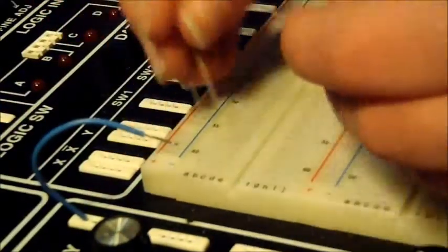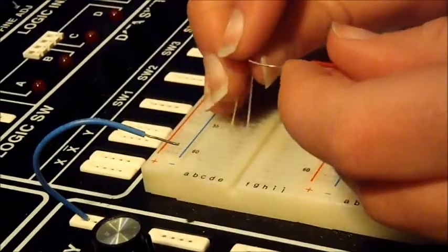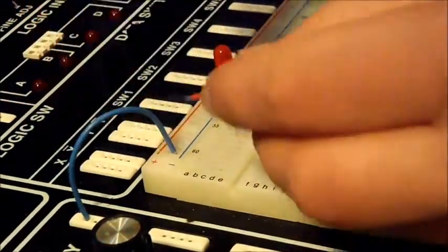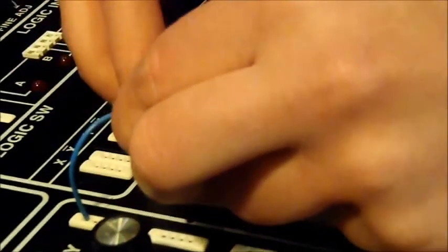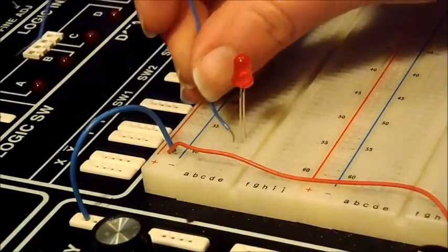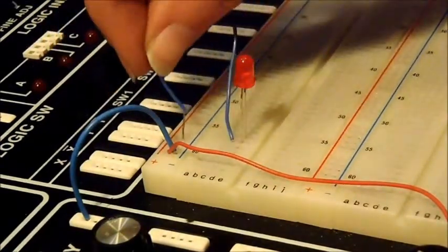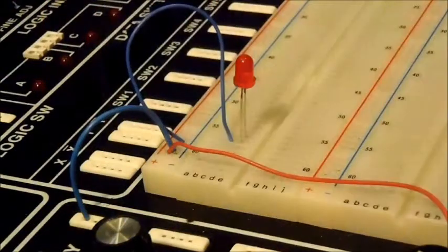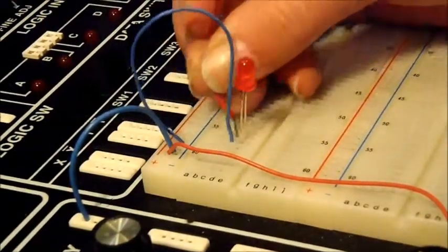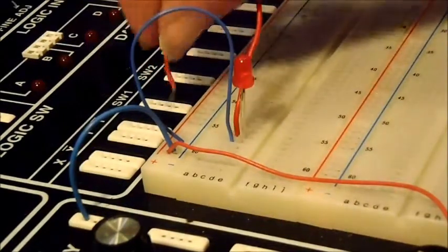So, you'll put the LED in one of these channels, hook up the ground and the power to the buses. Alright, since the negative end is in this channel, you'll hook that to the negative bus. And the positive end is in this channel next to it, so you'll hook that to the positive bus.